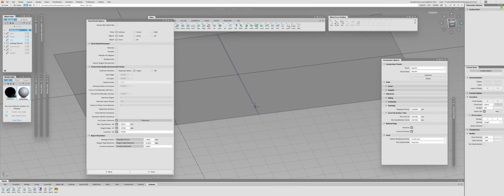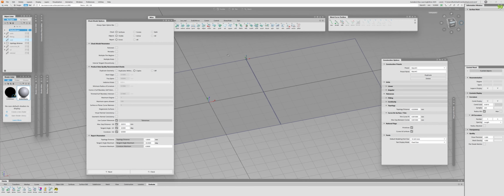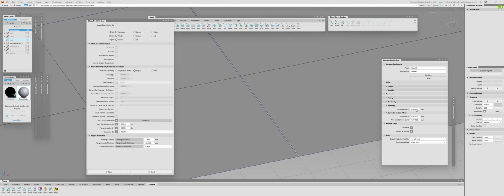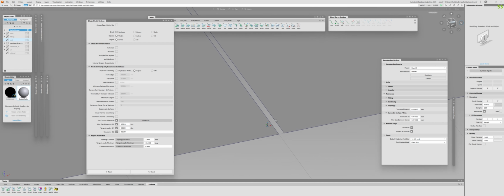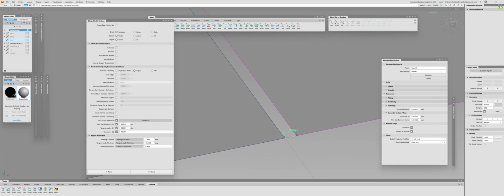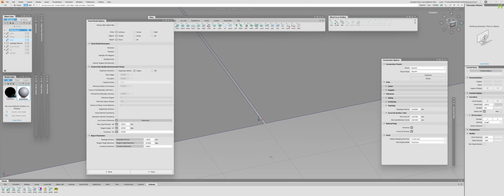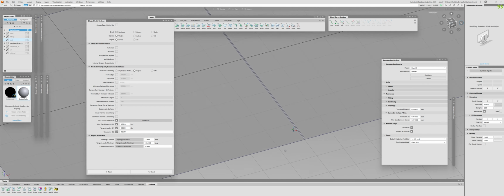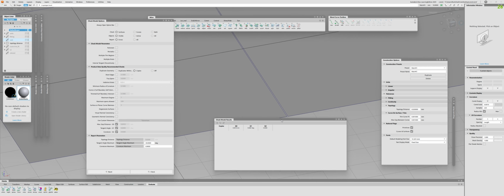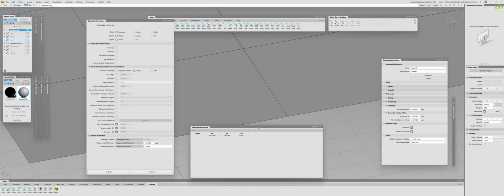Now we use the check model tool to evaluate our models for different types of errors. As you can see, my topology distance is set to 0.02. It's pretty tight. My gap here is pretty big. Now I don't know how big it is, so let me just measure that. My gap is 0.3 and the topology distance is 0.02, very small. So that means that if I use only my topology and perform the check, it will not return me any errors whatsoever,